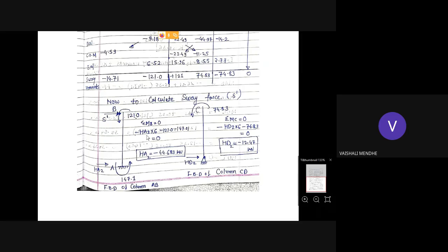So you don't have to consider any external loading acting on that frame. That is only due to the displacement. So this 40 kilonewton external loading I have not shown here. Maybe that loading is acting on the member or joint, but that was considered in the non-sway analysis, so don't consider it in the sway analysis.